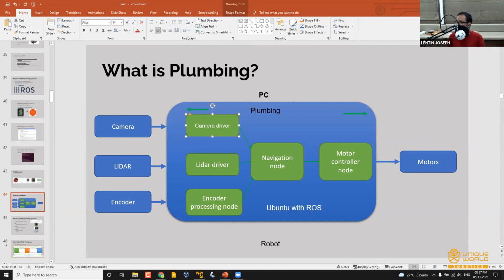And here he mentioned launch files. Launch files are a way to run many nodes or programs in a single command. If you want to start these 5 programs in a single command, you can use a thing called launch files in ROS. So basically the heart of ROS is the inter-process communication. I hope this is clear to you. This is the important part of ROS: it helps you send and receive data between different processes on the robot computer.